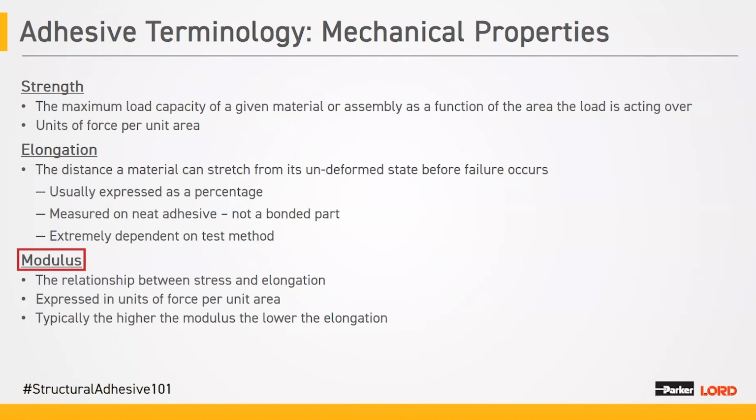Modulus, this is often listed and used from an engineering standpoint where customers can begin to design a part. It's simply the relationship of stress versus the elongation. It's expressed in a force per unit area. And typically the higher the modulus, the lower the elongation.